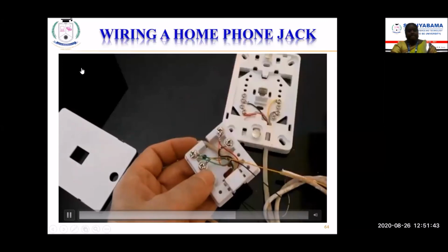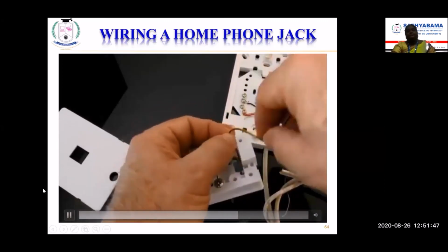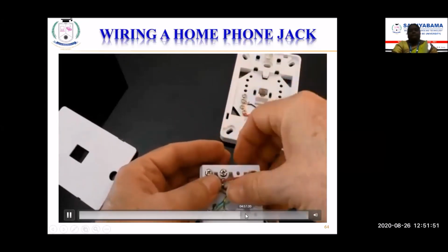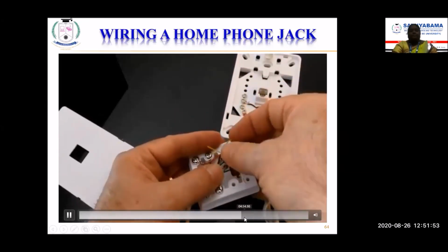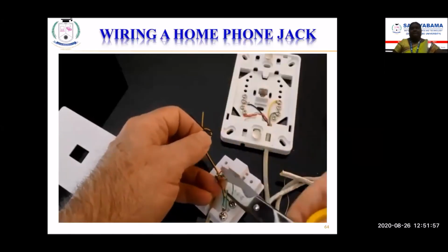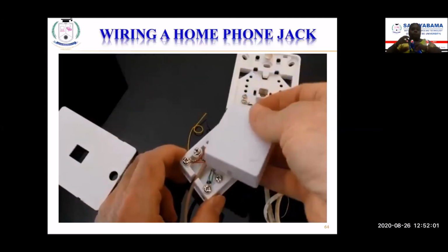See how I just kind of wiggled it off until it broke off? All right, if you're not going to use these, you can either just cut them, or you can loop them up and just stuff them inside here like that. That way, in case somebody needs to come back and use those pairs. I'm just going to cut them off right now. All right. And then you want to put your cover back on, and you're done.